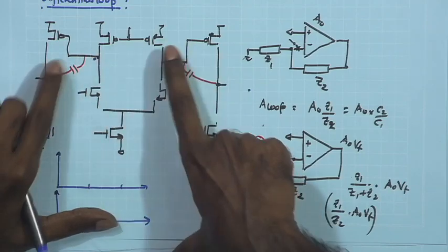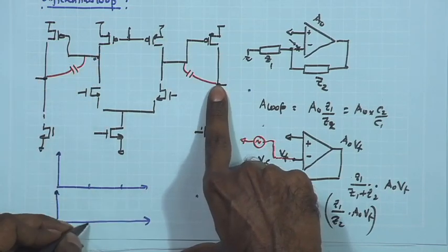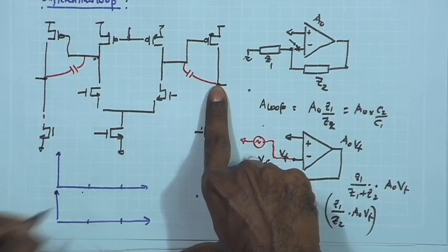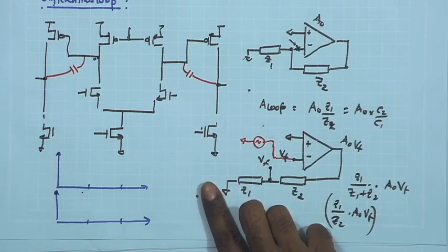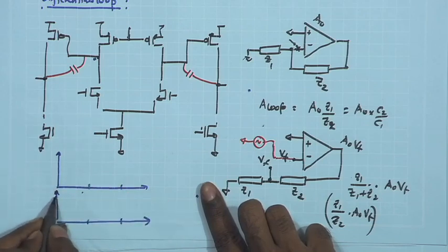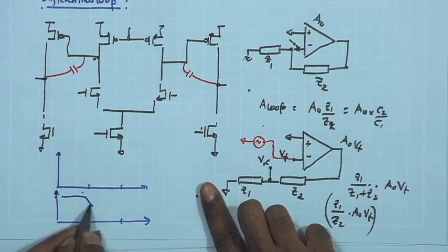Therefore, the overall poles at these 2 points will remain almost close. So, if I look at the phase response, it should be more or less similar. So, overall phase response, if I look at the first point, it will be showing 90 degree, and the second point approaching 180 degree, something like that.